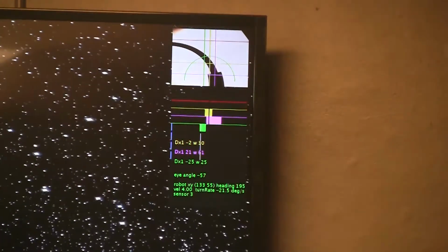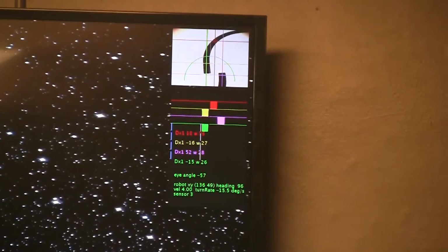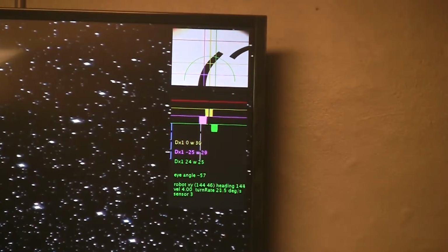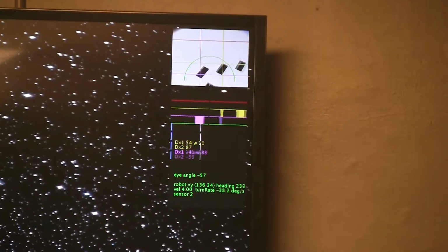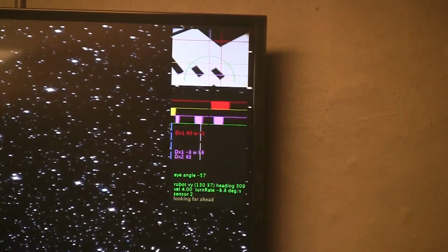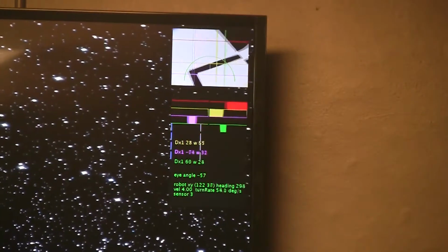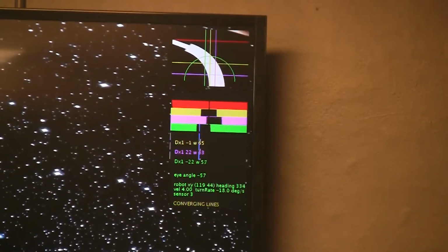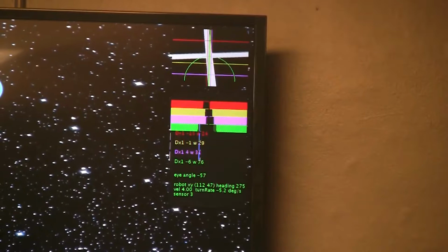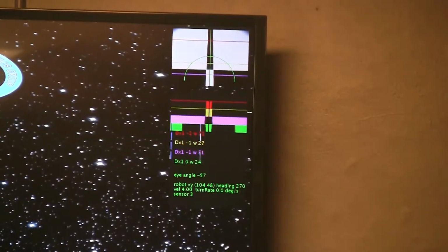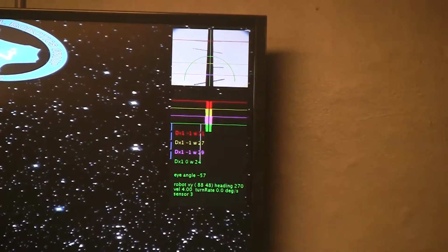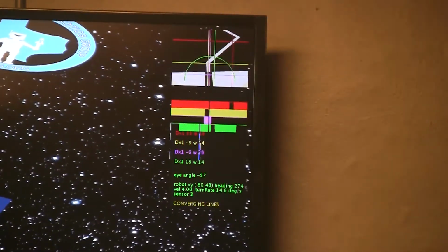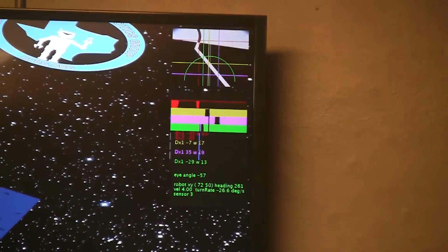So you're not using those as waypoints, you're just using them as markers to indicate how well it's tracking. Yeah, exactly. The other stuff we were seeing, the little pink looking things all over the place, those are part of an algorithm to look into the future and see the line out front. That relies on the robot having reasonably good odometry, at least long enough that those crumbs, when they come into view, will be in the right spot, if that makes sense.